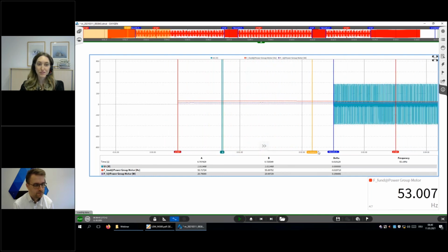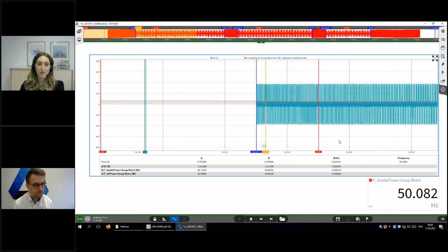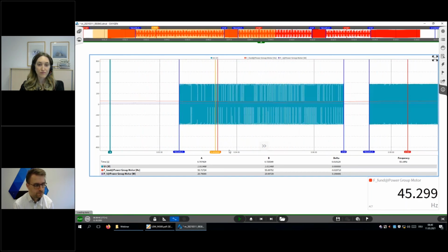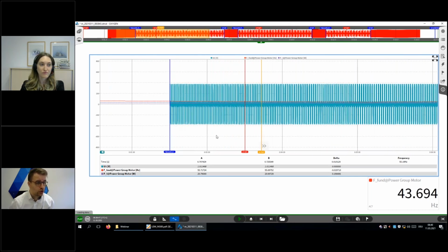If we come to this point, we leave the window and we also record the raw data. Exactly. So that's just an example of how a trigger could look. If the frequency is below 45 or above 55 Hertz, where it maybe should not be, we can trigger and have the raw data recorded because something happened that we did not expect or would not like to see.